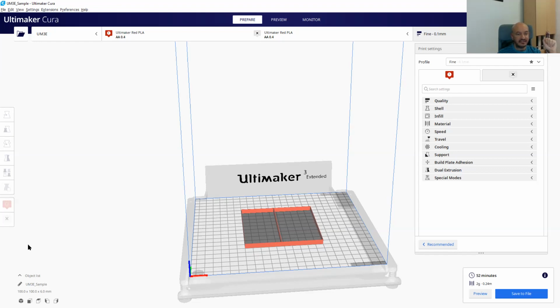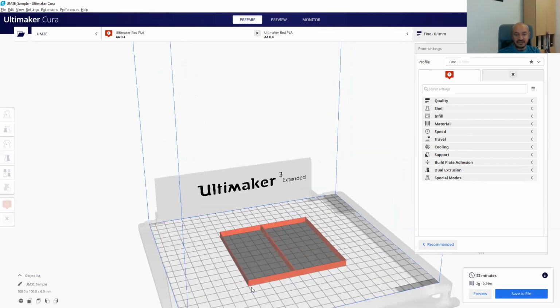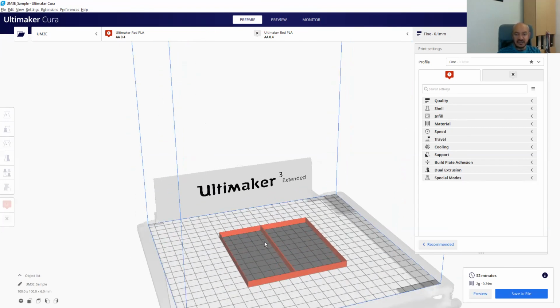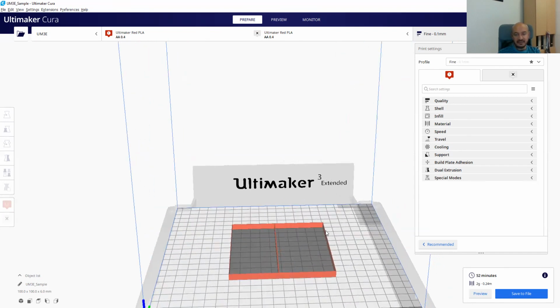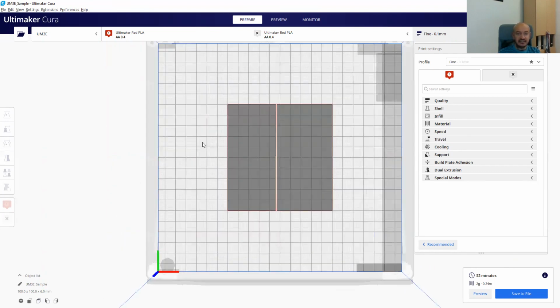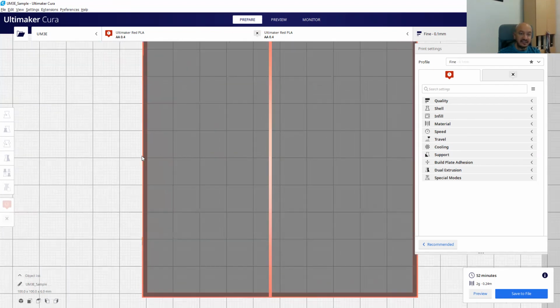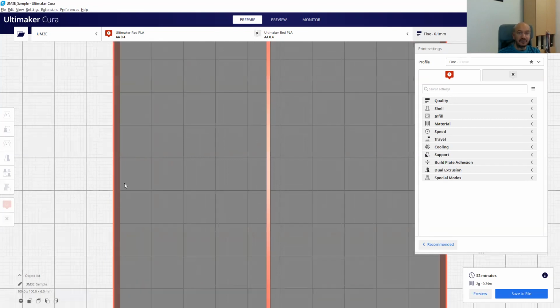As you know, in this project, you're about to manufacture or design shell-like structures. You will have a kind of polygon, and that will be a line. So that's a simple example which we can produce with the same project. So I have designed a rectangle, a square, and there is a line passing through the square, and I set the thickness to 0.4, which is the nozzle diameter of our 3D printer. This thickness of the STL file is 0.4.